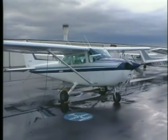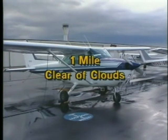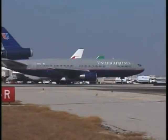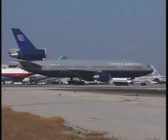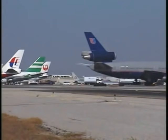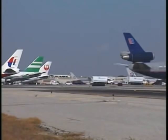This allows you to take off and land as long as you have 1 mile visibility and can remain clear of clouds. However, a special VFR clearance cannot be issued at night unless you have a current instrument rating and your airplane is equipped for instrument flight. In addition, special VFR clearances are not issued to fixed-wing aircraft during the day or night at some of the nation's busier airports.